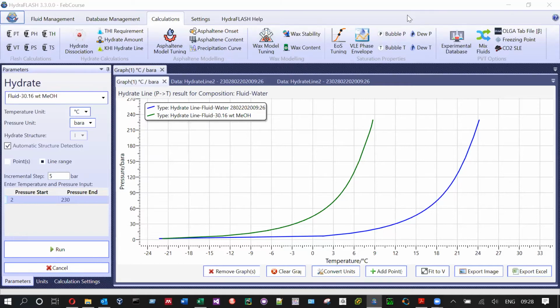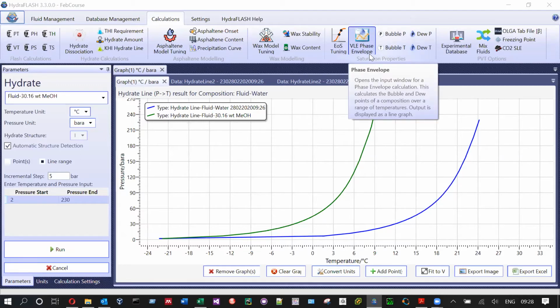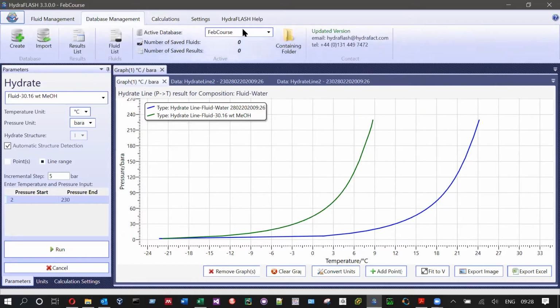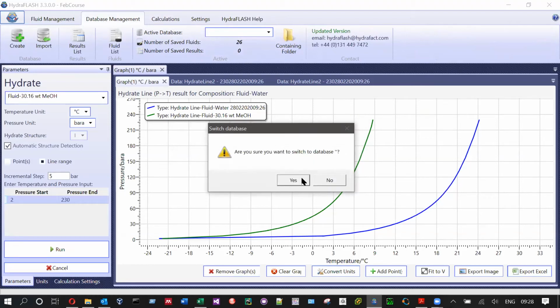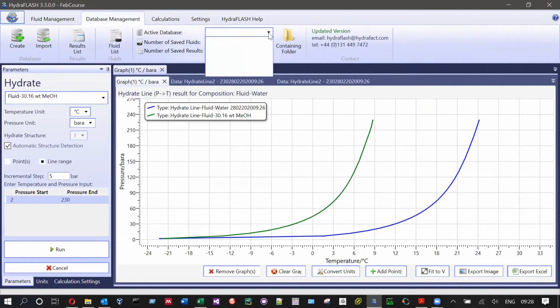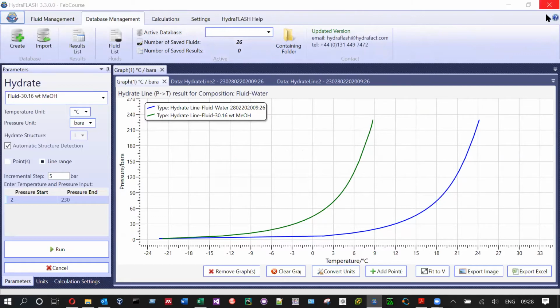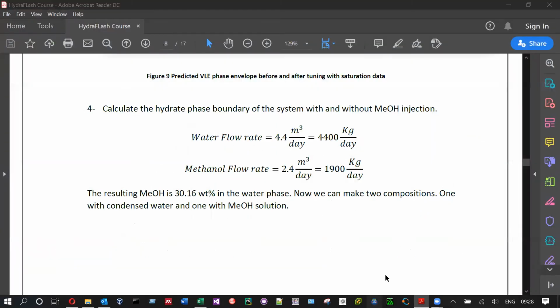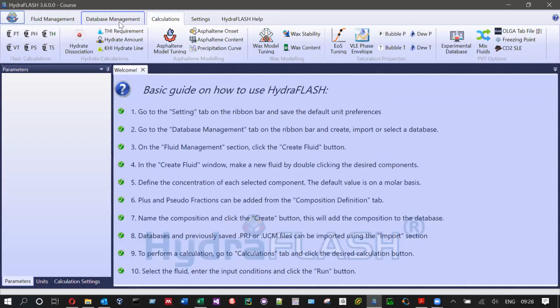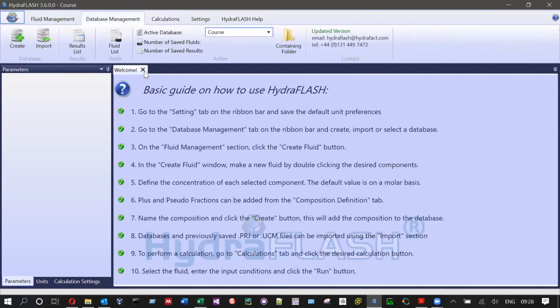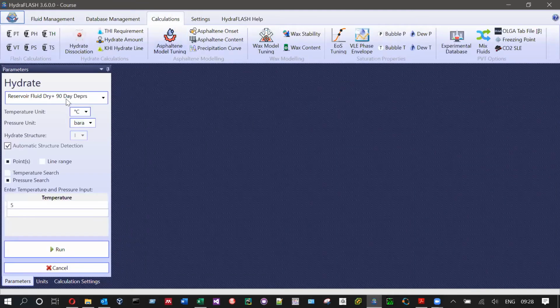What I want to add to the point you mentioned is that, because they initially thought it's a hydrate problem, they were doing depressurization, because depressurization is a very effective technique for removing hydrate. Clearly, they were not thinking of a wax problem, because depressurization does not do much about wax.